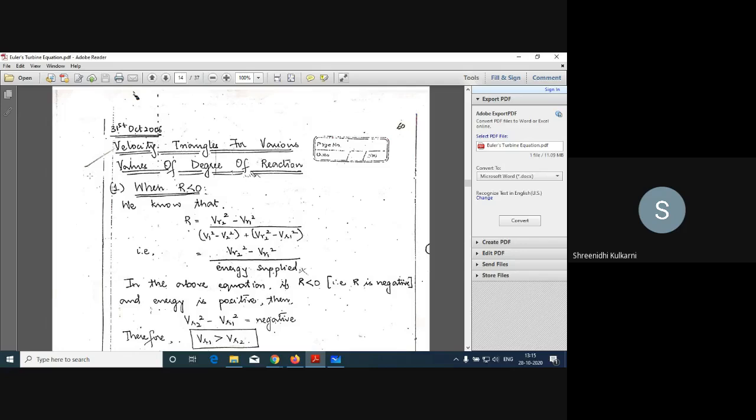What we'll get means the different velocity triangle. So for this, please remember the degree of reaction for axial flow turbines. Always remember the equation. Here I consider R, the degree of reaction, for an axial flow turbine, because for axial flow turbines U1 is equal to U2, which means that will get cancelled.